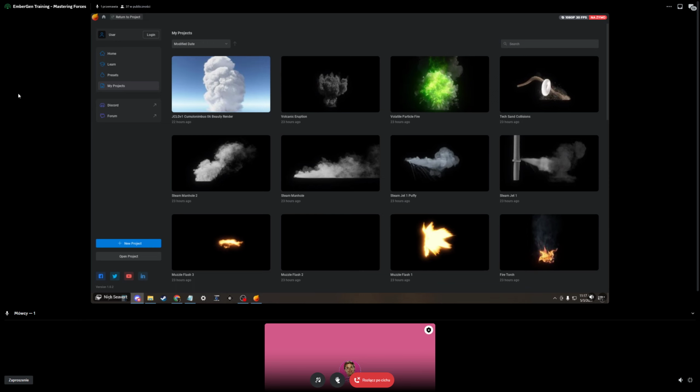So if we went here and changed our noise scale, you can see how this is reducing detail in the sim. If we lower the scale, it's going to add more frequency and subsequently give us more detail. You can also add more octaves. So if we look over here at our noise preview, as we add more octaves, at first it's blurry. You add more octaves and it adds more noise. And so it's basically just adding smaller and smaller noise layers on top of each other as you add more octaves, which is pretty cool. You can also increase your amplitude, which is basically the strength of the noise.